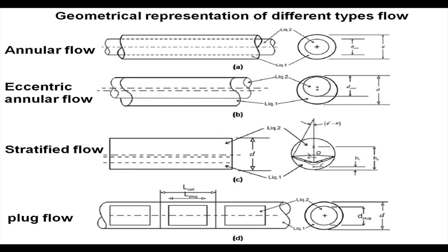Now, since we are working with small diameter systems, we have assumed that the interface separating the stratified flow will be a curved rather than a plane interface, and we assume that this curve is a circular one. The analysis for developing the equations for stratified flow has been taken from the analysis of Brauner et al., which can be found in the reference of the paper which I have already referred.